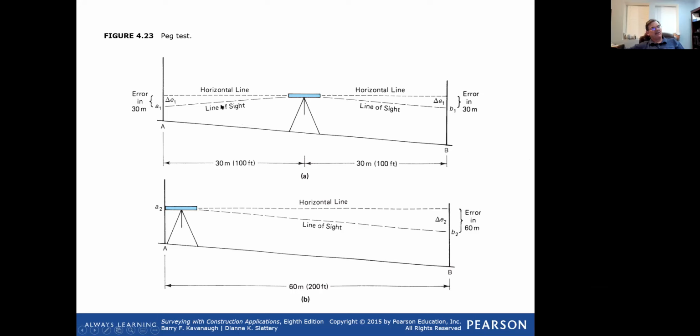There's error that's in here. When you then come over here and move from this one down next to the first shot you took on A, you get close. This distance here might be 4 or 5 feet. That's all you need. Maybe if you get closer, fine. You take a shot right here and you get a distance of like 4 or 5 feet. The amount of error in the gun is negligible at this point. It's too close for you to worry about it.